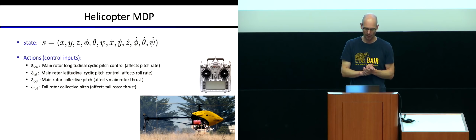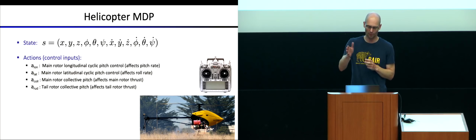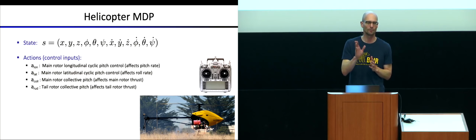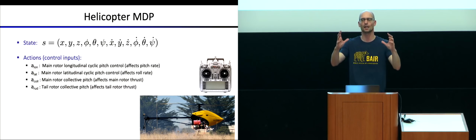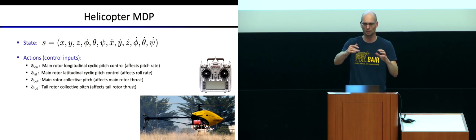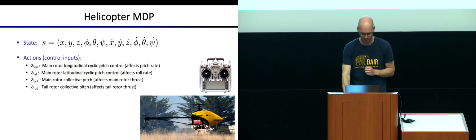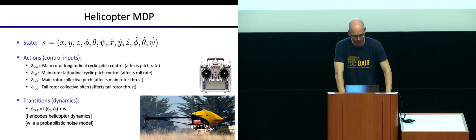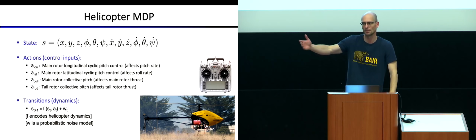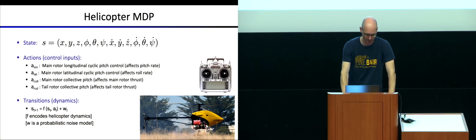So that's how you control a helicopter. You cannot directly ask it to fly forward or sideways. If you want to fly forward, you got to rotate nose down, and then you can accelerate vertically in the helicopter frame, but vertically in the helicopter frame will now be partially forward and partially up, and the up compensates for gravity, and the forward is what lets you fly forward. So you can build a model for this from collecting data from your helicopter, let's say, and learning a bunch of parameters that predict the next state given current state and action.